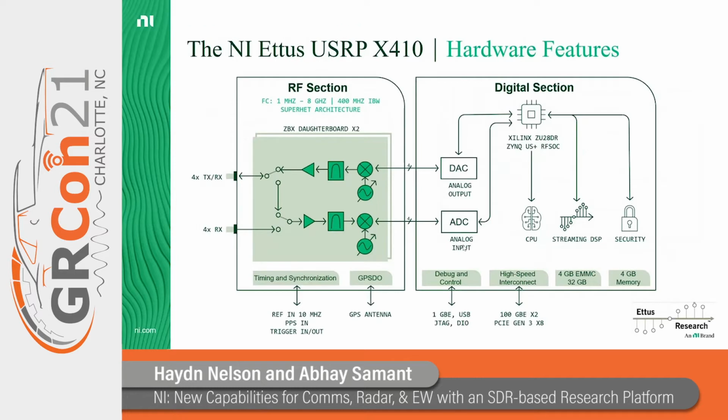What's inside this chip is really cool because it's more than just an FPGA. It has ADCs, DACs, a highly integrated device with embedded processors. It has 4 application processing units, 2 real-time processing units, and a large streaming DSP fabric. It has 8 multi-gigabit transceivers for high-speed digital interfacing.